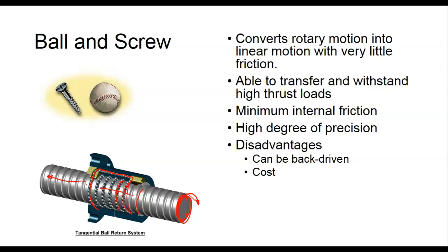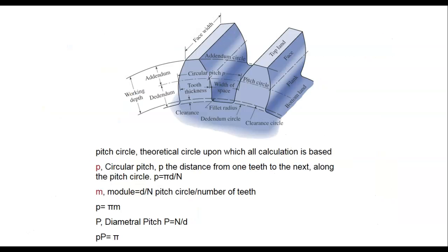The only problem is they don't work real well on vertical loads like this. They have a tendency to do what? Back drive, or move back. But horizontal works fine. This ball screw is actually what's driving the carriage that takes it from the distribution over to where the height sensor, the ultrasonic sensor, is. The Festo line doesn't use any of these.